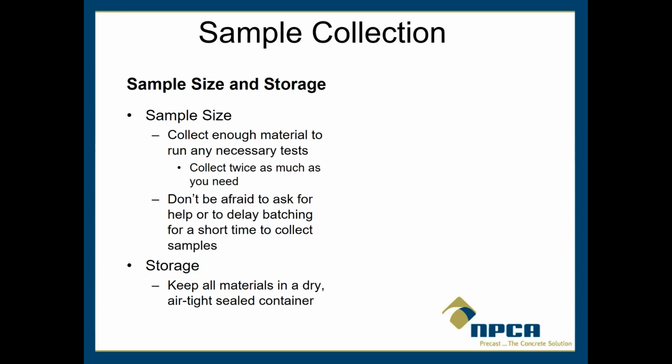Question often comes up, how much of a sample should I collect? Well, enough to run the necessary tests. And if you don't know all the tests that may be run, there's plenty of information out there. I'm sure you can consult with someone to let you know about possible tests, whether it's petrography or whatever it may be. But whatever that is, get about twice as much as you need for that test.